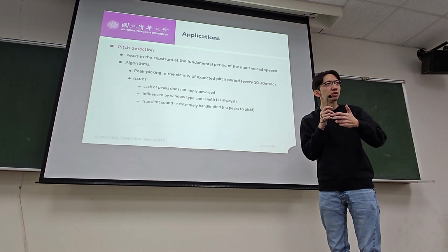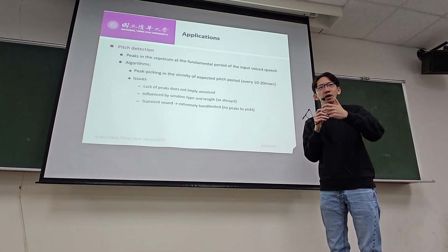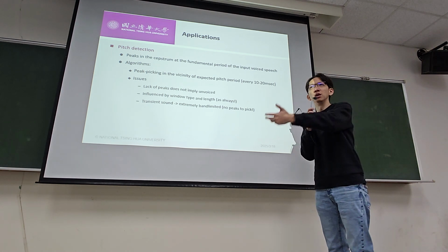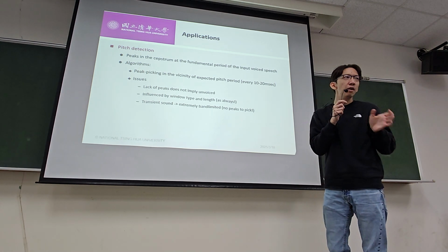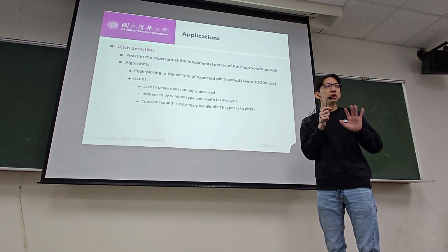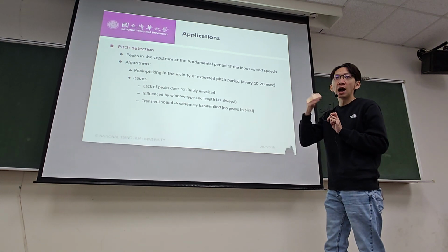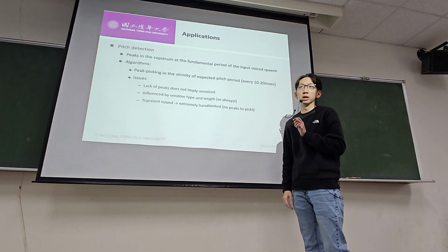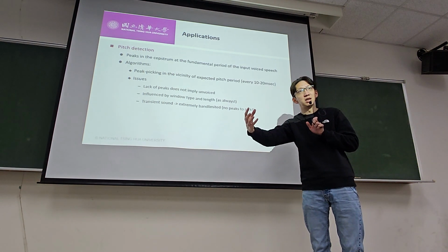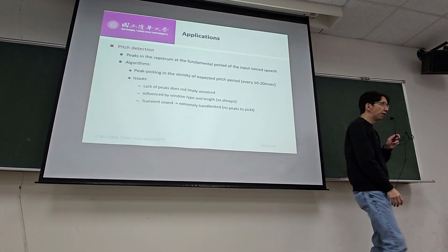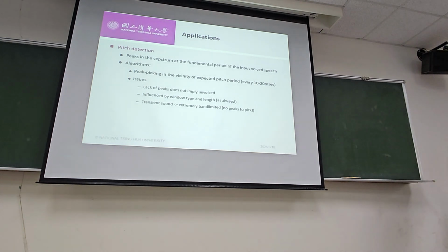What you're doing essentially in cepstrum analysis is only taking the log and then doing another transform. Right, taking the log and doing another transform. So everything you know upfront, every operation you do with Fourier analysis of the speech signal, will have the same effect if you do it in the cepstrum domain, because the cepstrum is the last layer of transformation with a log inserted. That's it. So everything you learned in the past few chapters will hold here.